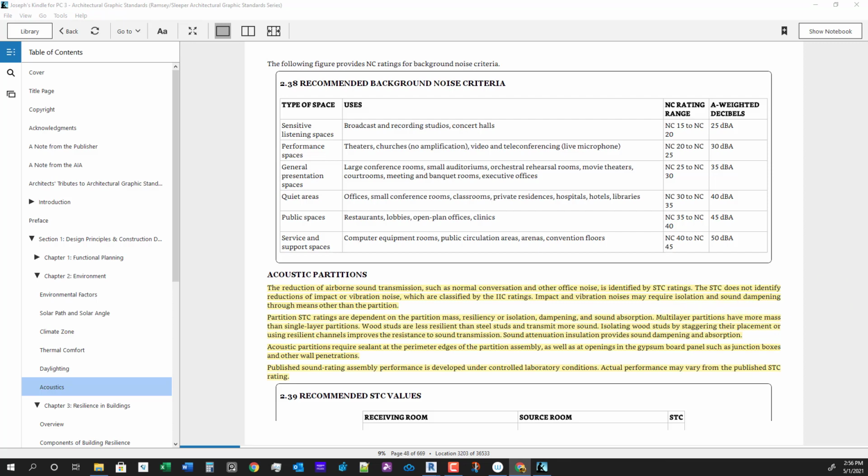So as you go through, depending on what area of architecture or construction you're working in, you have to be cognizant of the fact that anytime you penetrate these sound walls, the same thing with the fire rated wall, there's special caulking and whatnot that will have to be applied to the wall if you do penetrate the wall with a duct or a pipe.